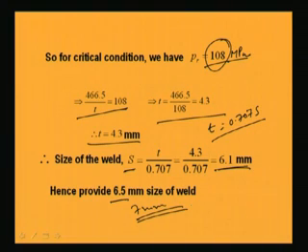So this is a typical example, we have gone through it so that we can understand how to calculate the stresses and what the procedure is, in what way we will calculate the resultant for a welded connection when the load is lying in the plane of the joint.